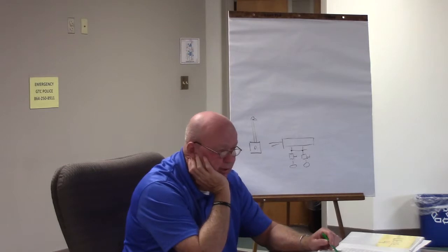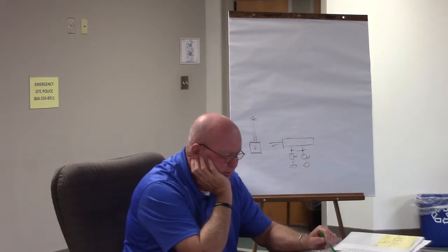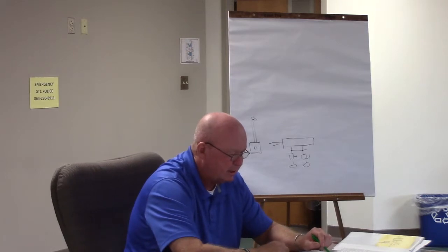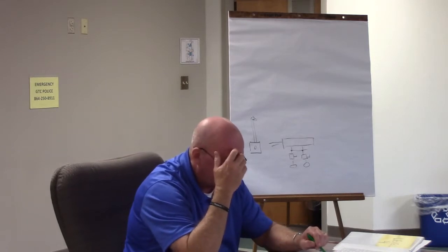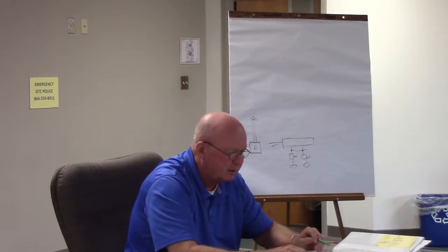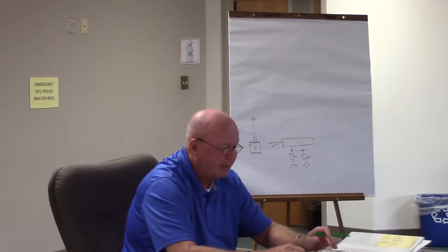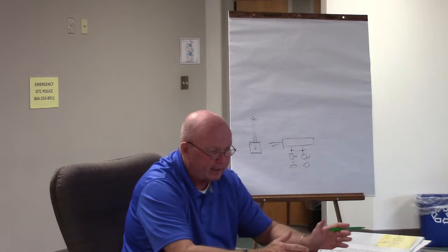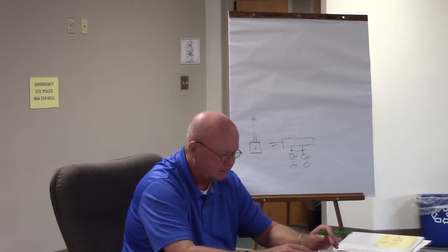220.44 for non-dwelling, 220.54 household electric dryers, 220.55 ranges, household cooking appliances, 220.56 kitchen equipment other than dwelling, 220.82 optional calculation for a dwelling, 220.83 optional calculation for existing dwelling, 220.84 multifamily dwelling, 220.86 optional method, and so on and so forth. So y'all get the gist of it. So demand factors. Because of that, you can see there are a lot of demand factors that actually affect the size of wire we use. So it comes into play.